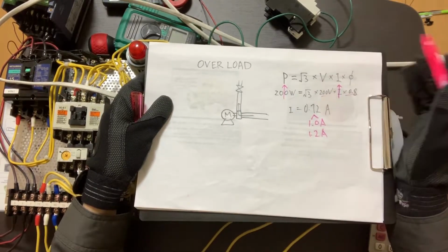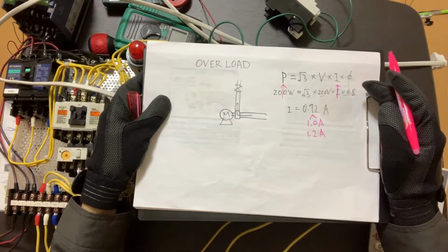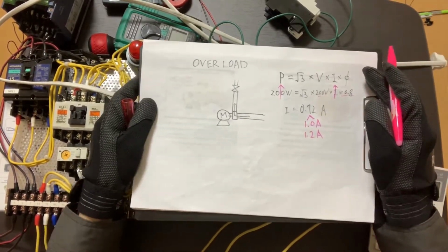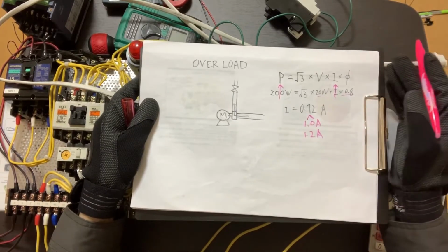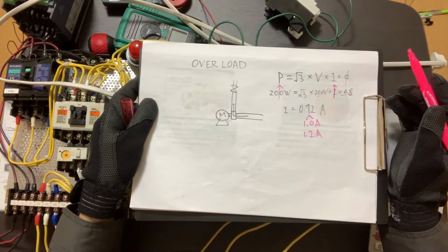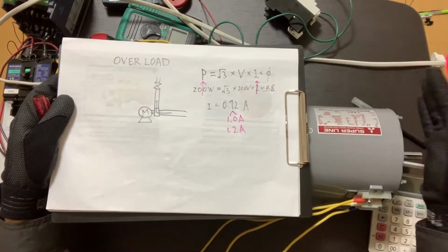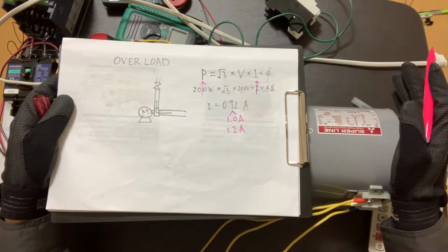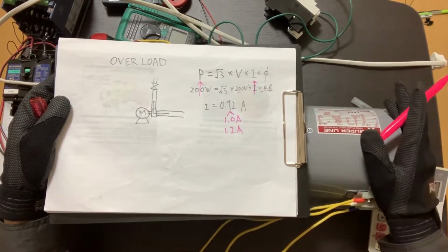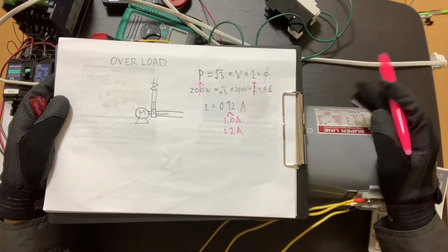In this state, there is a possibility that the motor burns out because the current turns into heat. The manufacturer does not guarantee safety with such overcurrent. So if overload lasts for a while, the coil heats up and some failure will occur, like insulation failure, coil interruption, coil short, or just thermal and mechanical breakdown.